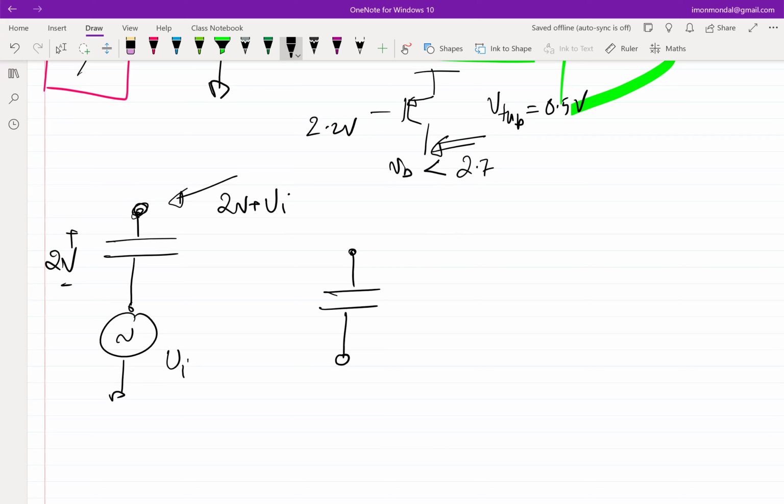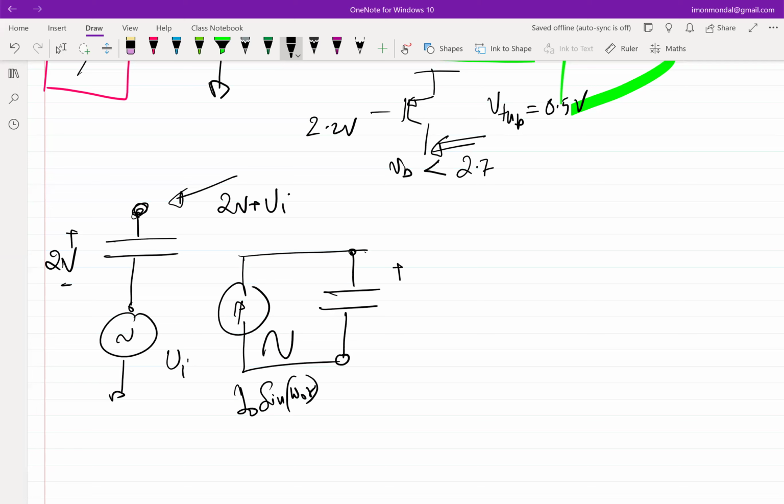Okay. So before we break, can you comment on this? We discussed this briefly a long time back. Seems like a long time now. So let's say I have a current source, which is sinusoidal. If this capacitor is supposed to act like a battery, in the presence of the sinusoidal current, that is I naught sine omega naught t, what should be the incremental voltage across the capacitor if the capacitor is supposed to behave like a battery?